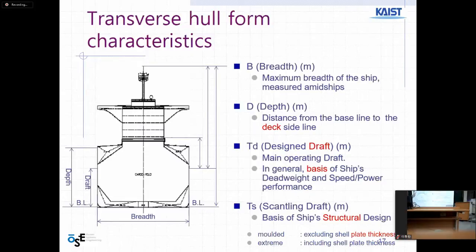They pour grain into the entrance, right? The shape looks like this way, this way. So without this shape, usually they have an empty space. And if you have an empty space, the ship is rolling, then the cargo is shifting. So that's why they use this shape. This can be used for another reason.